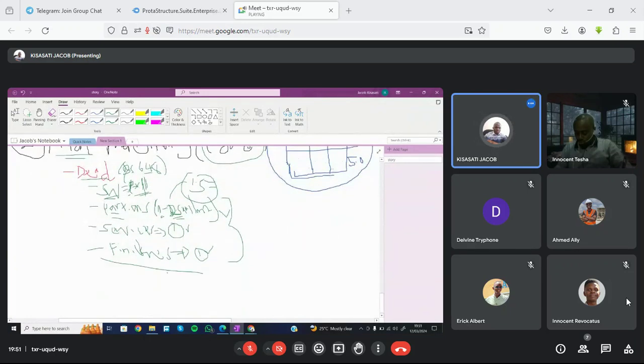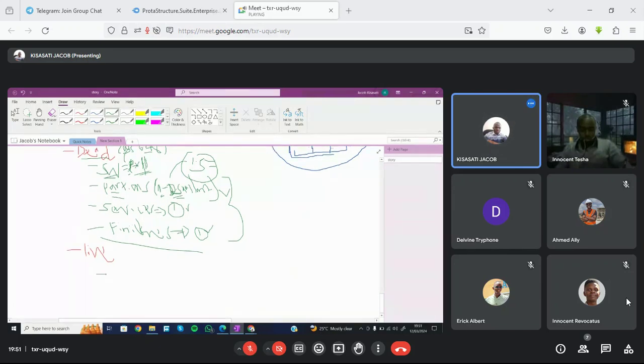We have got the dead loads, so now what do we look for? Live load. So how do we get live load? So we have live load. Live loads I will not write in full, this is understandable. So for the live loads, where do we get them, or how do we calculate them? This one you'll go to BS 6399 part 1, then table 1.